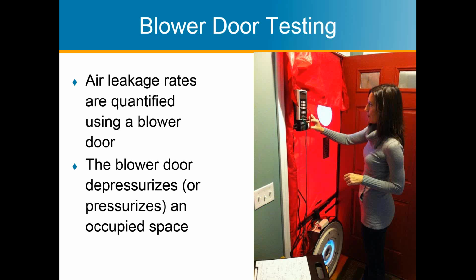It's very rough, but it's something people can relate to. With 200 square inches, you can convert that to the size of a basketball or a volleyball or a golf ball, and tell people this is how big of an air leak there is. That's kind of why you're there, right, to fix that, to make that basketball into a volleyball size hole, because we never get all of it. But that's essentially what a blower door is doing.